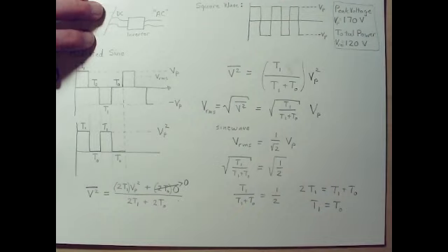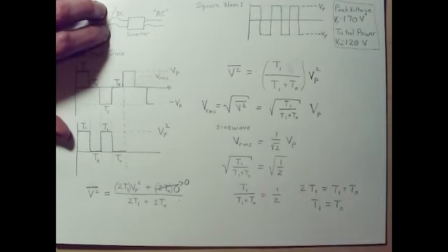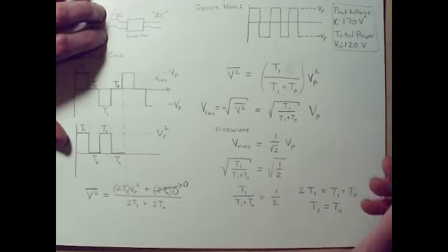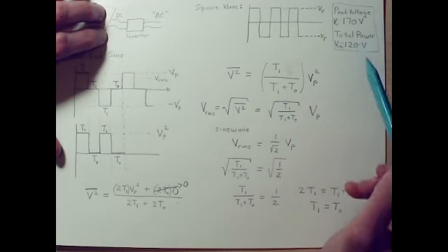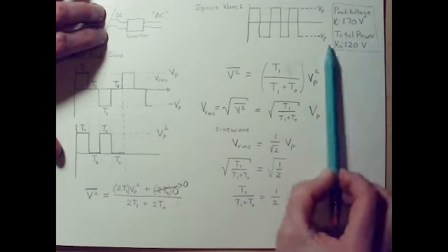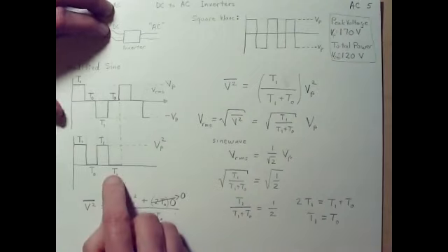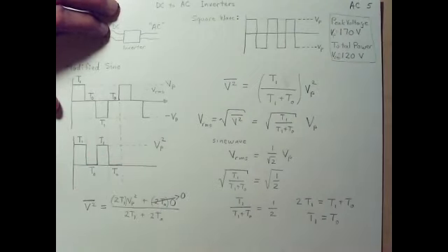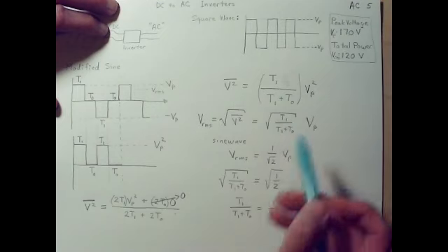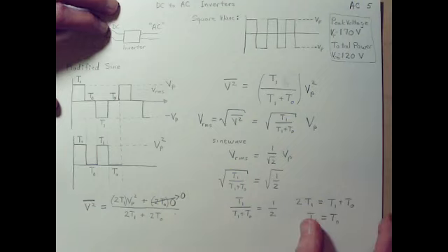can plug in a device that uses the peak, like a computer. Most electronic devices actually just use the peak voltage. At least older ones do. TVs and such. Whereas something like a light bulb or a heater, a toaster, things like that, they depend on the RMS voltage. They're using all of the power all the time. So now, using this modified sine wave, you can plug in both kinds of devices. And you can set VP to be 170 volts, and then the RMS will be exactly 120 volts, and both types of devices will work correctly.